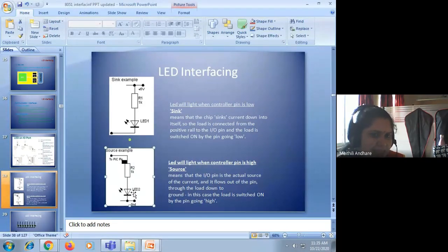So now you can understand the two possible ways of connecting the LED. In the practical, if you have connected it this way, the external examiner may ask, can I connect it in the other way? You may be under the illusion that the LED can be connected only one way, as in the write-up or the practical. No, there are two possibilities, as two leads are available, but accordingly we have to make changes in the diagram and in the logic, and only then will the LED glow.